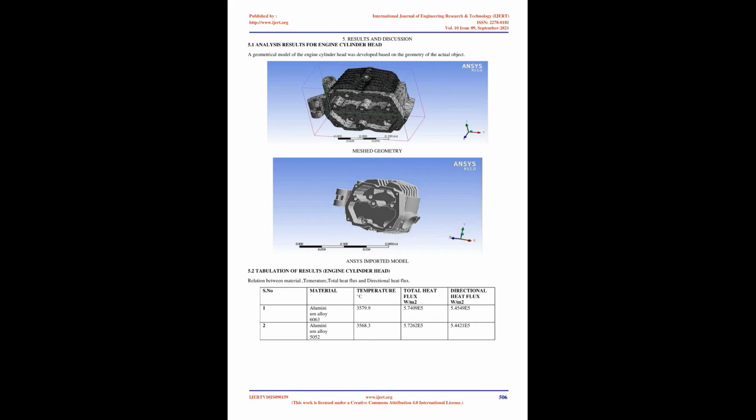It uses a second opposed piston in each cylinder which moves at half the cyclical rate of the main piston, thus giving 6 piston movements per cycle. It does not use any additional working fluid. After the exhaust stroke, instead of air/fuel mixture, as in case of petrol engines, fresh air is sucked into the cylinder from the air filter, and is removed during the 6th stroke.